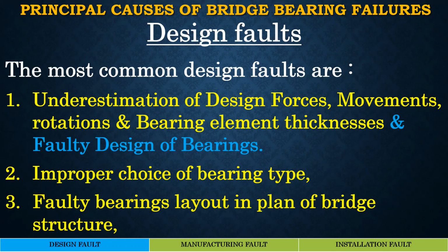This drawing is passed on to the bearing manufacturer or vendor, who does the detailed design of the bearing, and based on this detailed design, the bearings are manufactured and installed. The second possibility could be improper choice of the bearing type itself. That means the layout of the bearing is faulty, and a faulty bearing layout in the plan of the bridge structure can cause serious issues.